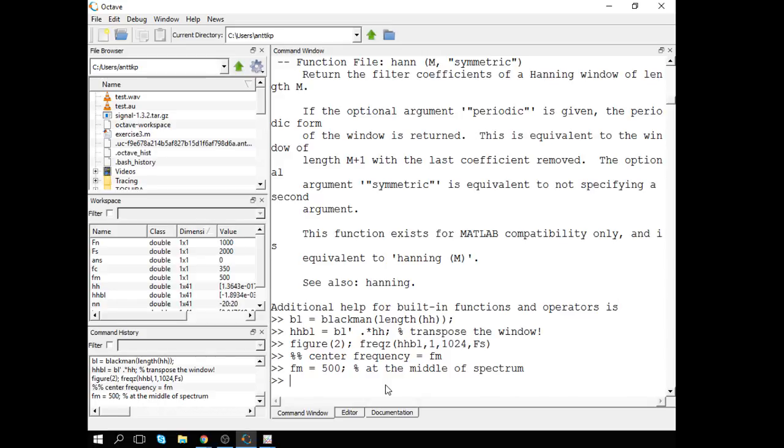So basically then the band pass filter would be 2 times HL. I will take the Blackman windowed sinc, modulate with cosine. I try to avoid the sine modulation because sine may have lots of zeros on it. At least at the middle there is 1 zero.